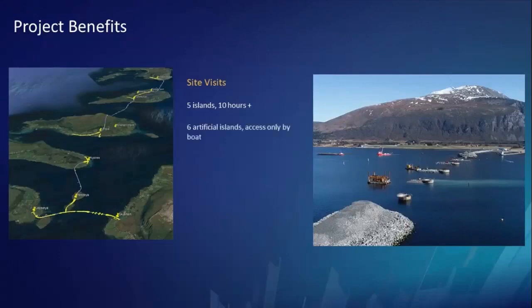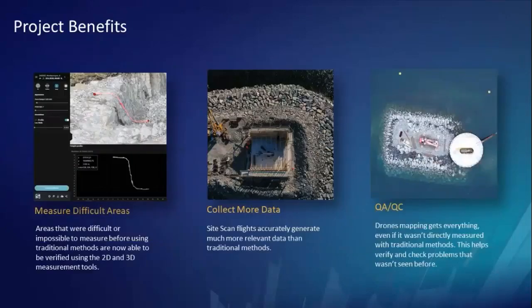To be in some kind of control over this vast and complex project, we needed to find a way to get the overview and data of what we are building. Basically, we needed to get reality back into the main office. So we started to fly and to generate orthophotos on a regular basis. We started with one drone, a Phantom 4 RTK, and started the drone mapping from every site about once a month, but soon realized that we needed one more drone, so now we have 2. We set up a geo server where we upload the orthophotos and give access to the whole project organization.